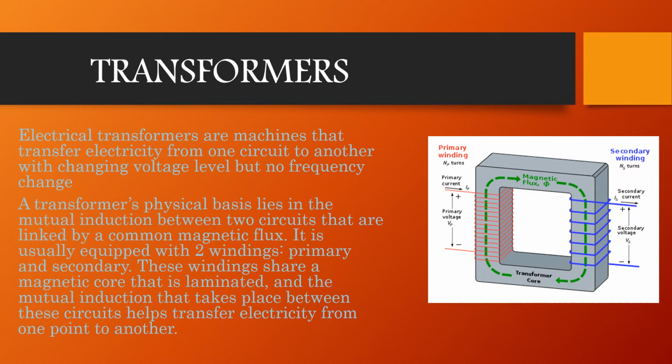Depending on the amount of linked flux between the primary and secondary windings, there will be different rates of change in flux linkage. To ensure maximum flux linkage, that is maximum flux passing through and linking to the secondary winding coil, a low reluctance path is placed common to both windings. This leads to greater efficiency in working performance and forms the core of the transformer. The application of alternating voltage to the windings on the primary side creates an alternating flux in the core. This links both windings to induce EMF in the primary as well as the secondary side.